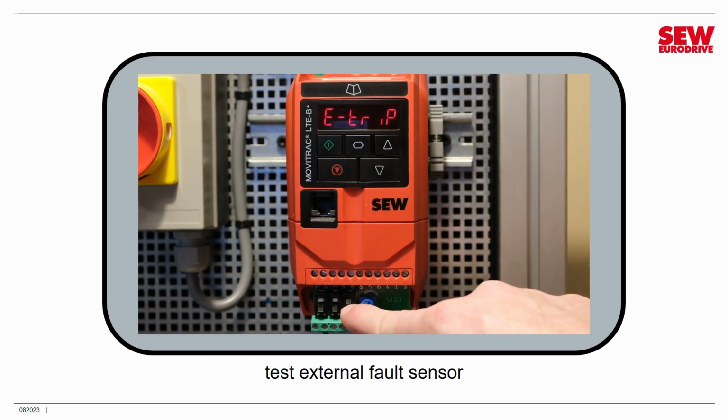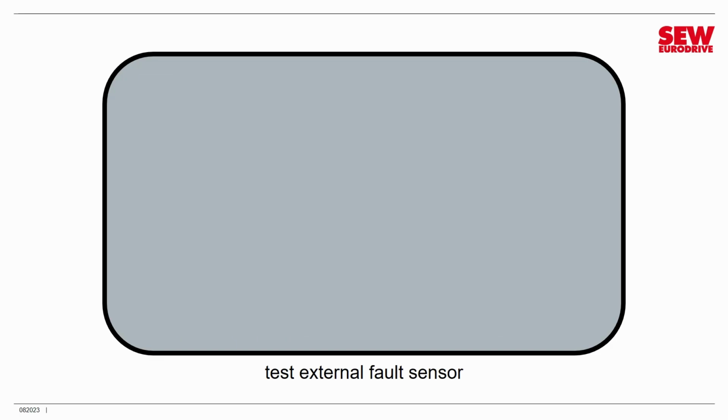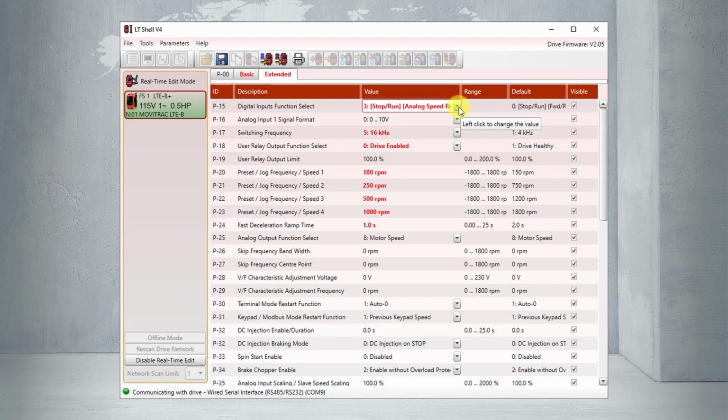Let's trip it again, and now clear it by turning DI1 off and then on. Again, notice it restarts immediately, so always be careful when you clear a fault because the drive could just take off without warning, and that could be disastrous. So think twice before you do that. Well, we can see that that worked okay. That's what you'll experience if you connect just any generic active low sensor to digital input 3 and put it in one of these variants.